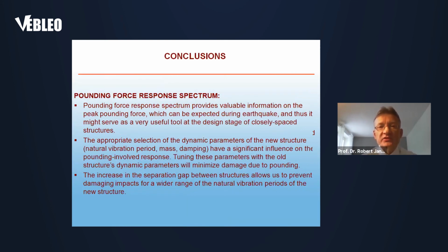Finally, the pounding force response spectrum provides very valuable information on the peak pounding force which can be expected during the whole time of the earthquake. Therefore, it might serve as a very useful tool at the design stage of closely spaced structures in seismic regions. The appropriate selection of the dynamic properties of the new structure, so natural vibration period, mass, and damping, has a significant influence on the pounding-involved response.